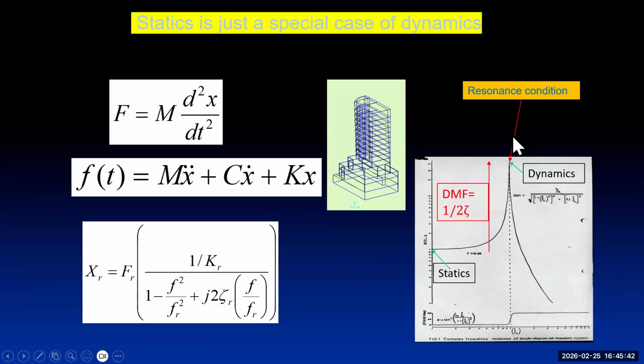When we looked at the response of the Cadet Chapel at West Point, we found resonance conditions which were causing the problem. And we found a resonance condition which was not identified with the normal sort of techniques of using something down at ground level. We measured up as well. And so we could see how the structure was behaving, and we identified where cracking would occur.